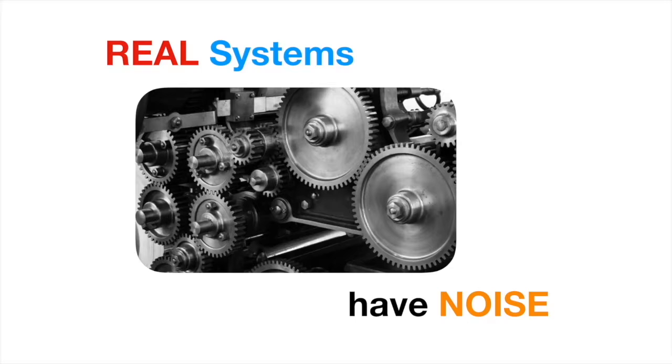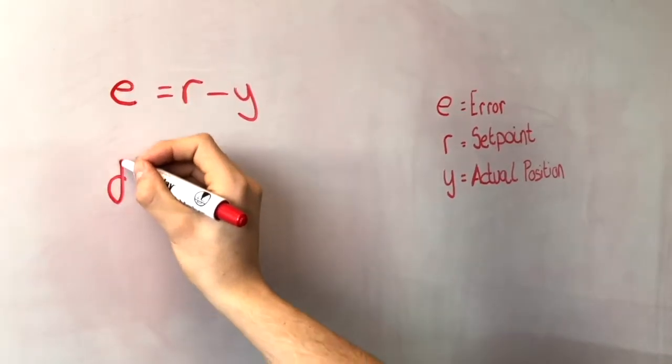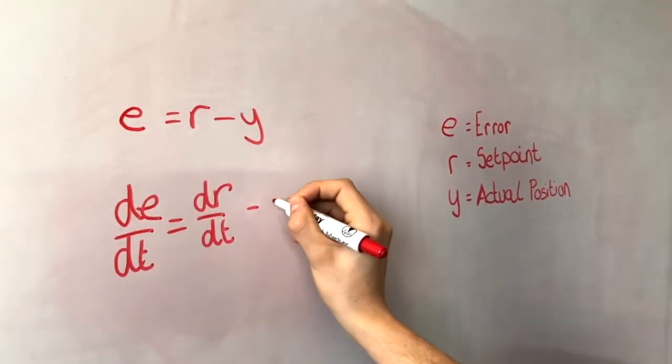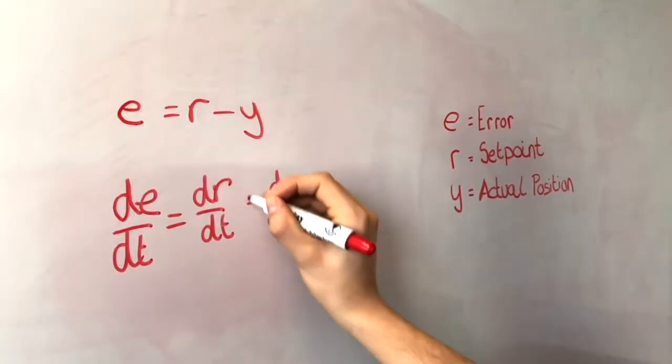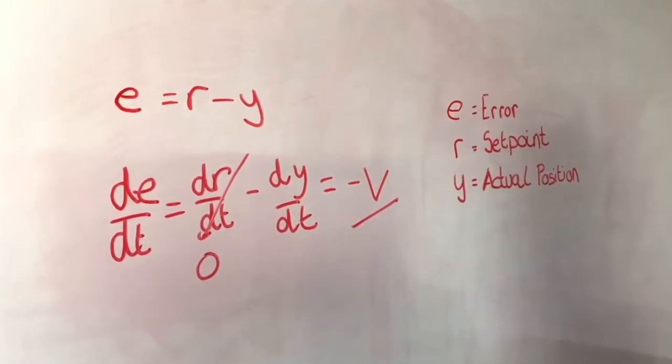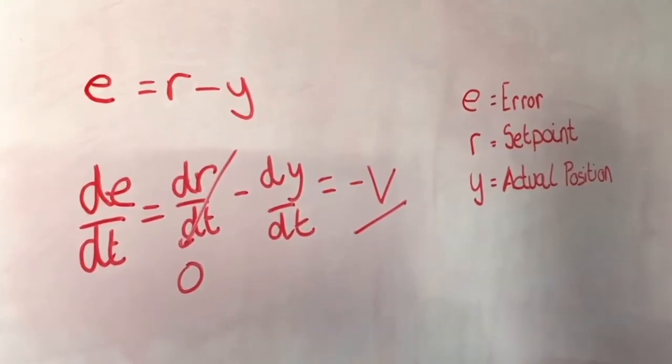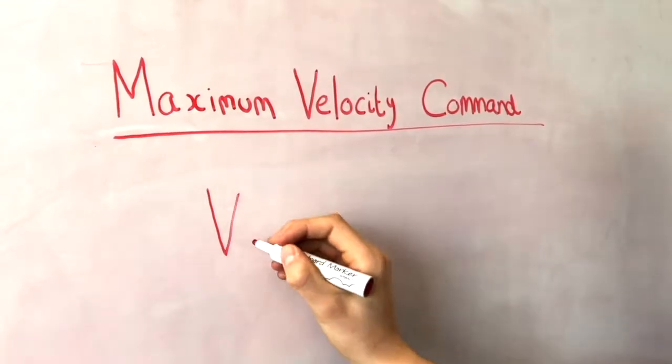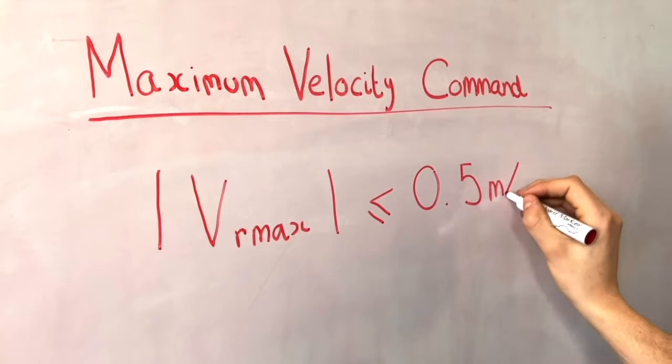Real physical systems and sensors are imperfect and subject to measurement noise. This especially affects derivative action, as it generally involves using numerical differentiation, which amplifies noise. This problem was circumvented by using velocity data from the IMU. This velocity is obtained directly from the sensor data and has less noise. Furthermore, for safety purposes, a form of saturation was introduced to prevent velocity commands exceeding 0.5 meters per second in any direction.